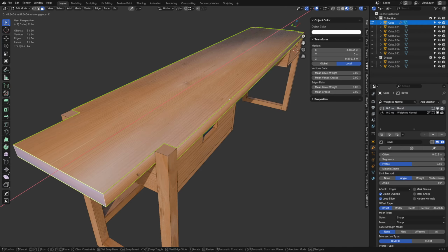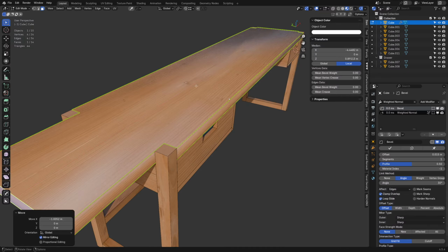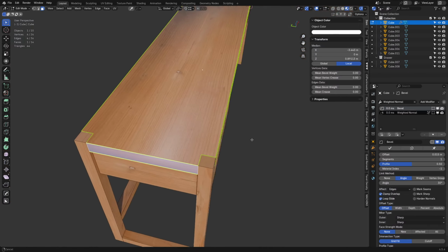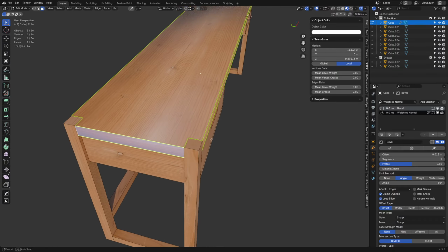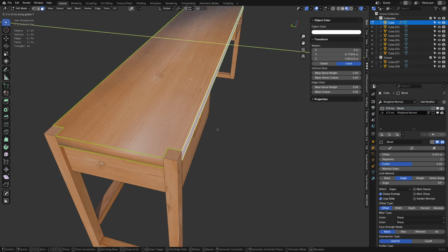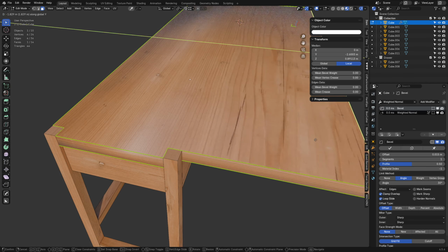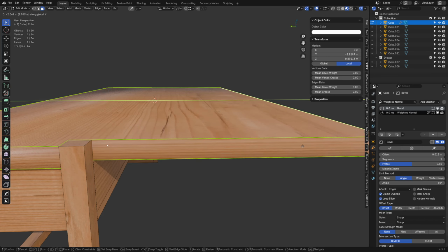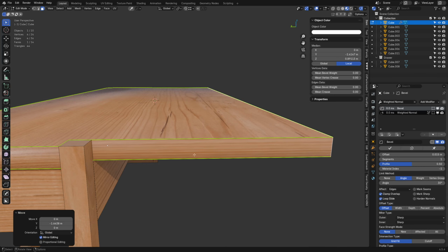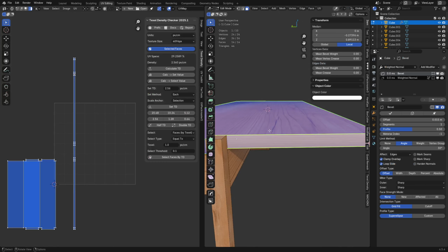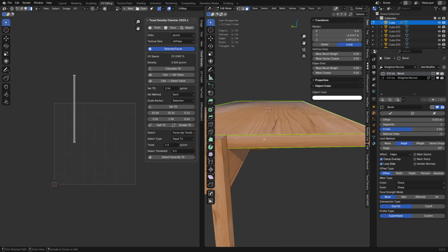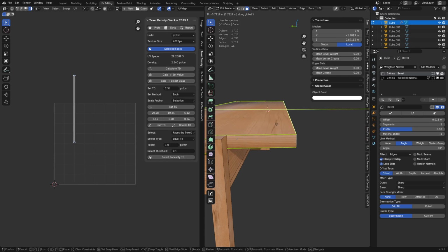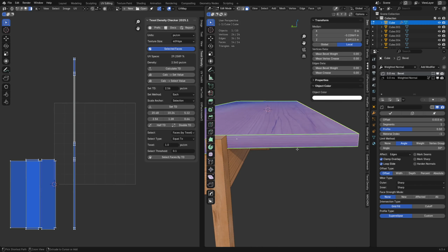But we can now move this and you can see the texture will still distort slightly. That's just how 3D models work. It happens in Maya and Max. It's all the same everywhere for the most part. But we can do things like this and preserve the UVs basically. And it's actually not just preserving them. It's like you're moving the UV itself at the same time while moving the model. So you end up extending the UV islands is what's happening. So when we look at this, we select this piece here, you can see this whole section was pulled out now. Originally it was like this, and we pull it out, boom, now it's like that, right?